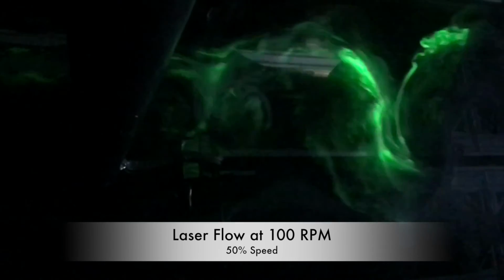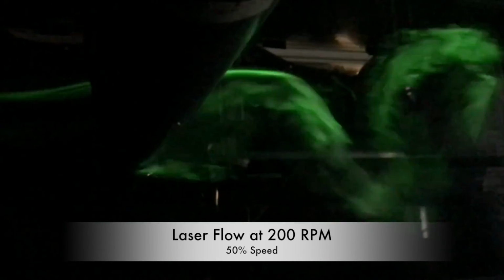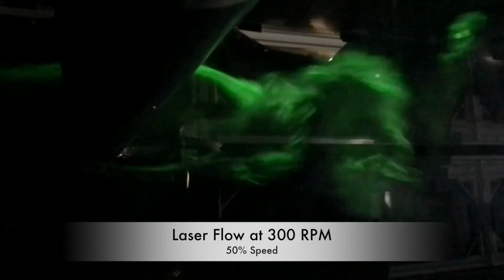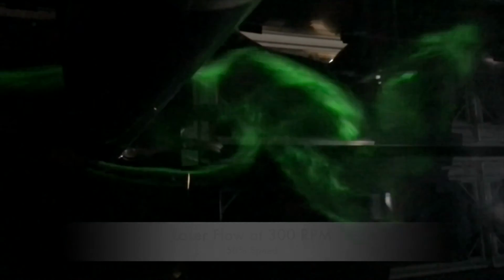Readings and videos were taken at 100, 200, and 300 RPM. Then, while the wind tunnel was at 300 RPM, the green laser sheet was positioned on top of the test section in order to better illuminate the smoke. Video and recordings were then taken as the wind tunnel was stepped back down.